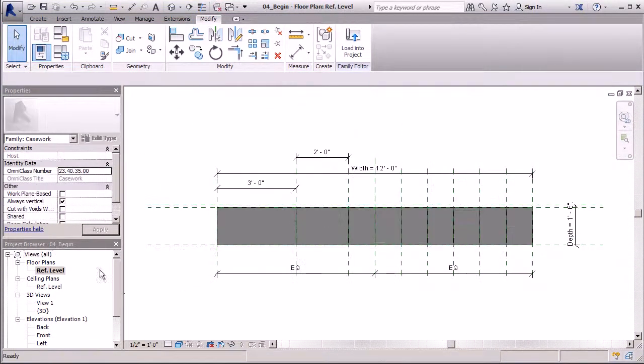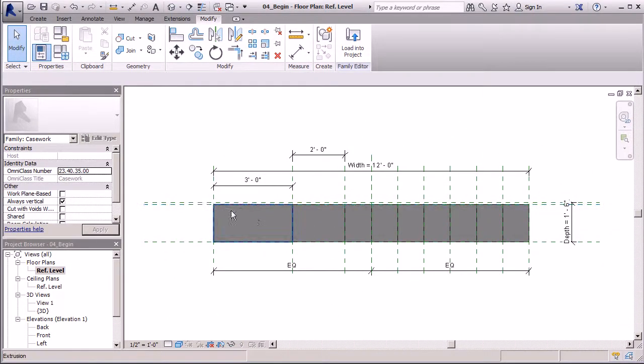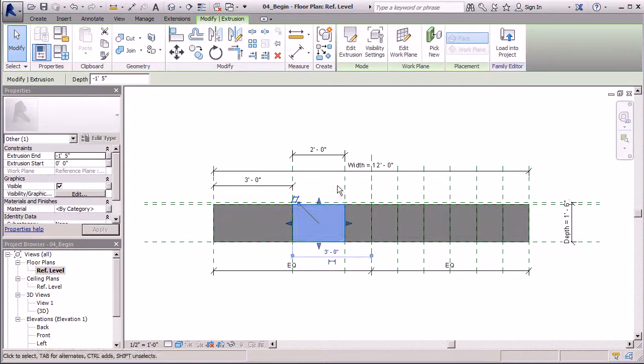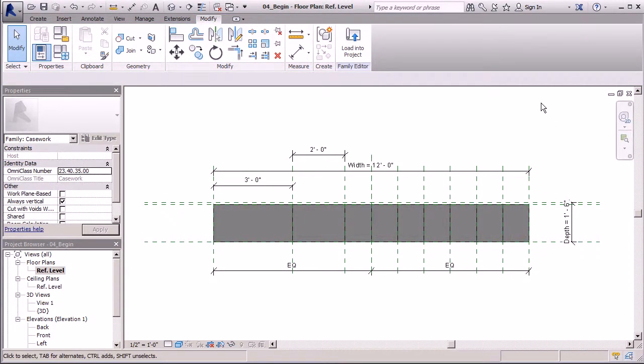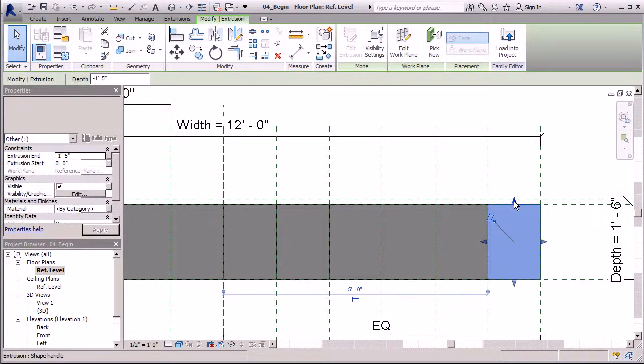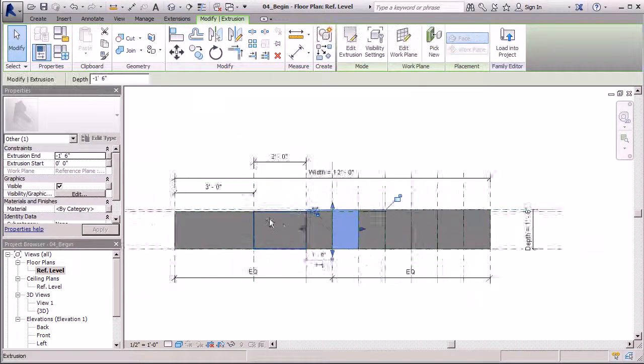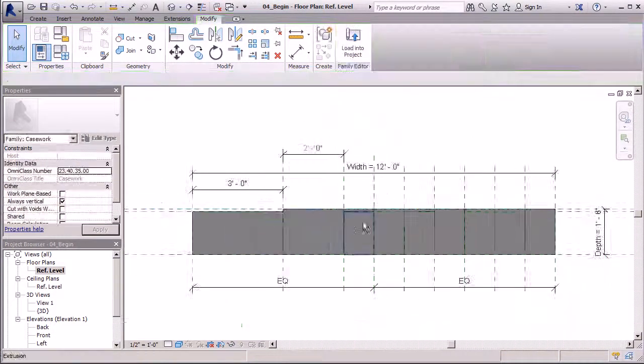Let's take the same approach to what's going on top. So I see we definitely set another plane to allow for thickness in the back, but I think we should extrude these voids back. That way, whenever we're creating the voids or additional voids within these spaces, we can stop them at this point here to allow for that thickness. So let's simply click on those and drag them all the way back here. Really easy process here. And this will definitely allow for that thickness for the backboard on our design here. And it's good we already set that reference plane.